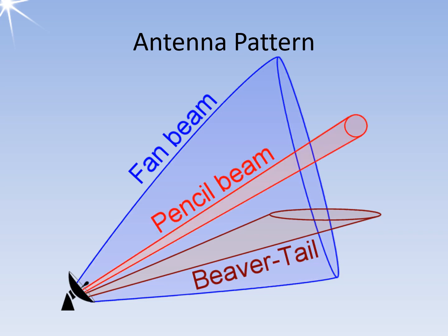Performing a narrow pencil beam scan would be too time-consuming for air defense or air traffic control radar. Such a scan can only be afforded by meteorological precipitation radar. In weather radars, the complete volume scan, which involves successive rotation of the antenna at several elevation angles, takes around 5 to 15 minutes. In air defense radar, multiple pencil beams can be generated simultaneously using digital beamforming. However, this involves significant technical effort and is still too expensive for air traffic control radar.